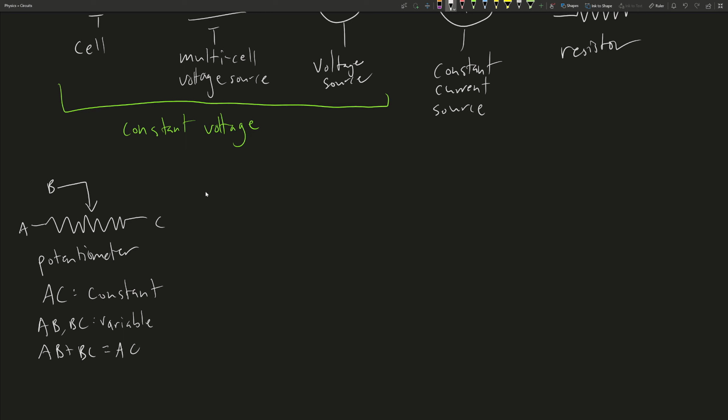Now, let's see, what else is there? There are also capacitors, which usually just look like two parallel plates of the same size. A battery or a cell would be two plates of different sizes, but a capacitor has two plates of the same size. Sometimes capacitors can be drawn with two curved plates, or you can have a curved plate and a straight plate, and that would be a polarized capacitor, which means that the straight part is positive. So the voltage across it always has to be positive, going from the negative terminal to the positive terminal.